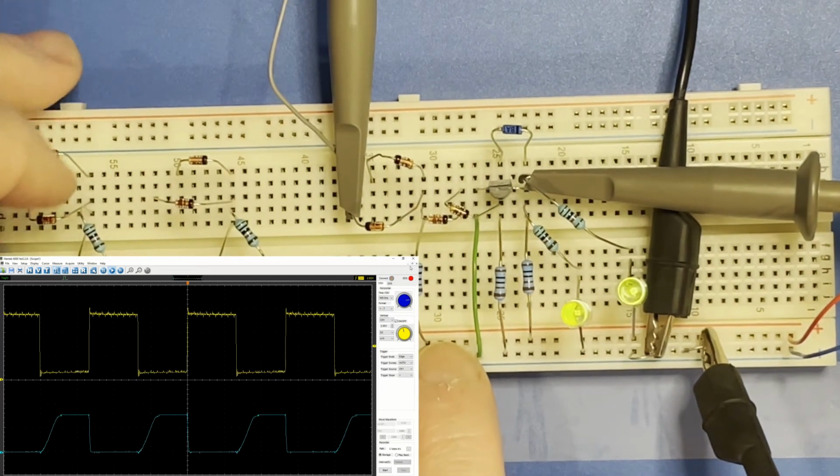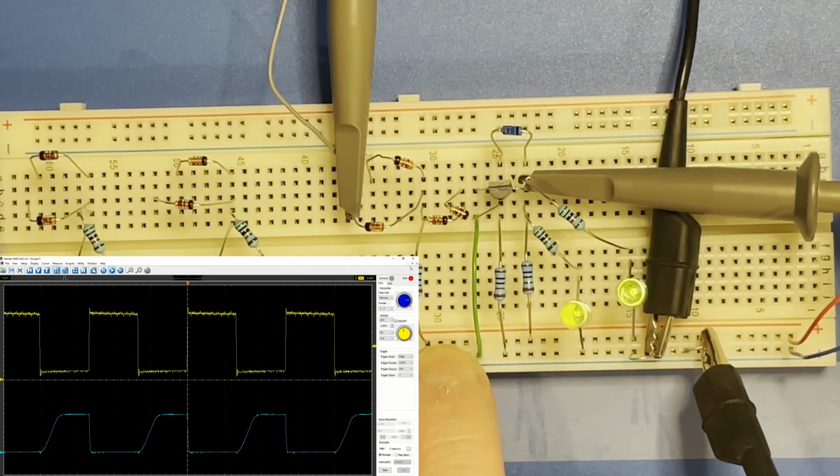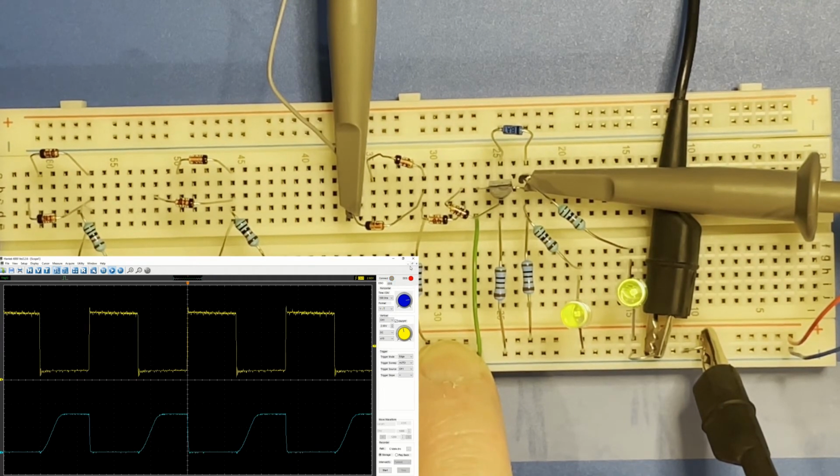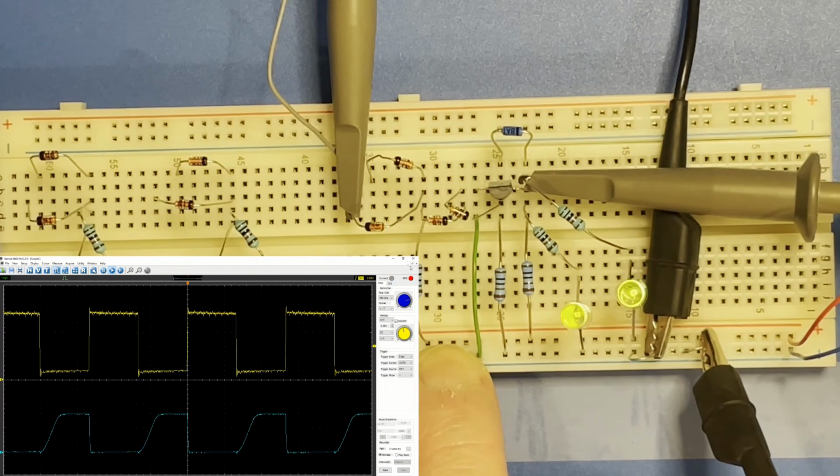It also works for things like opto-isolator transistors. If you're ever trying to put a fast signal or even a moderate speed signal through an opto-isolator, such as working with MIDI data or serial data, adding a Schottky diode between the base and collector of the transistor in the isolator will vastly speed up its response.